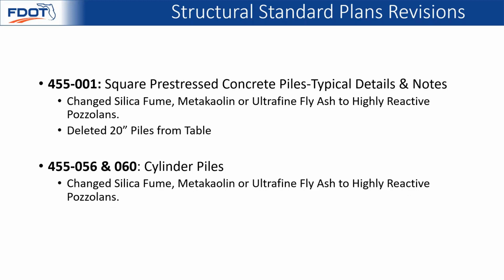Now, last year we did some changes with the silica fume, metakaolin, ultra fly ash to highly reactive pozzolans. This year we went through and found some more. So I think we have them all. And the other change we made on the 455-001 was deleting the 20-inch piles from the table because we deleted the standards.